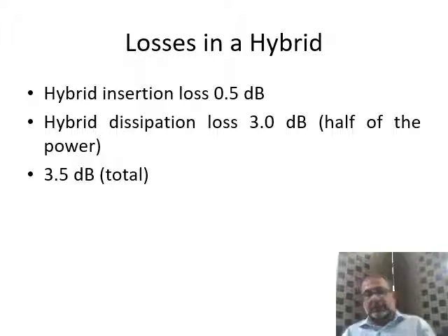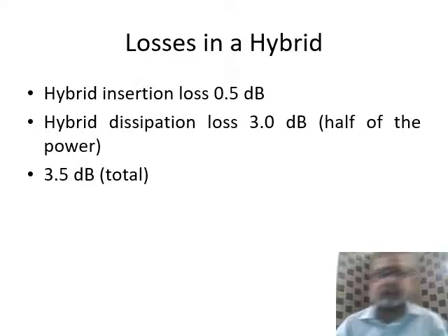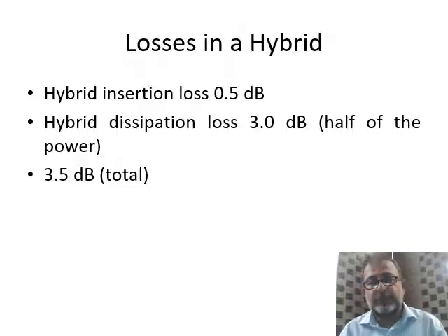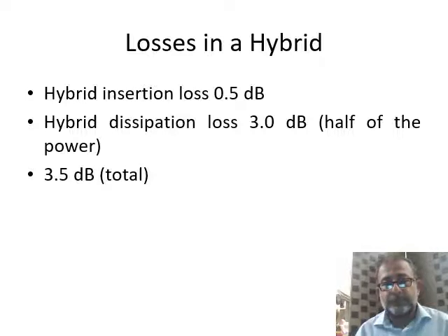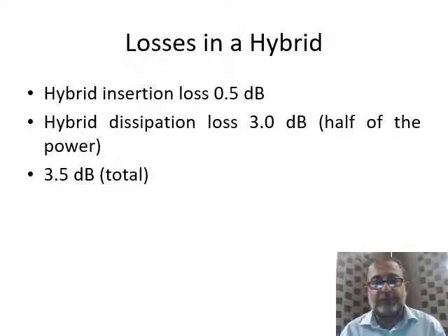But there is a negative side to it also. First of all, the hybrid insertion loss of about 0.5 dB, and hybrid dissipation loss, which is approximately 3 dB, which is half of the power lost as hybrid dissipation.